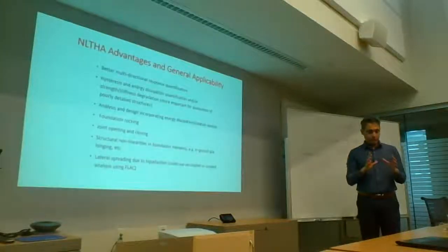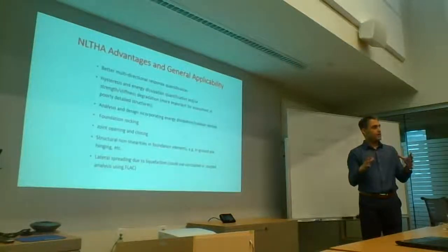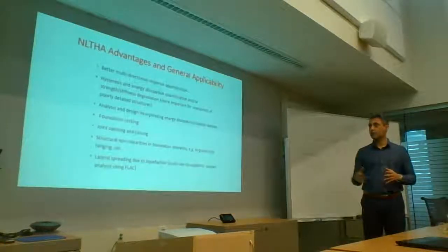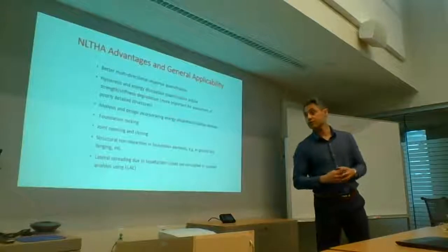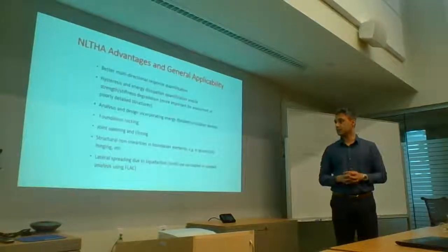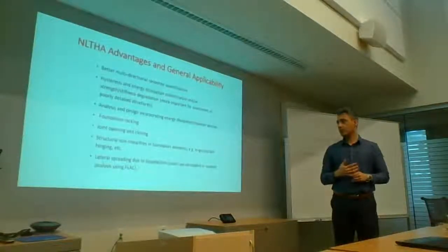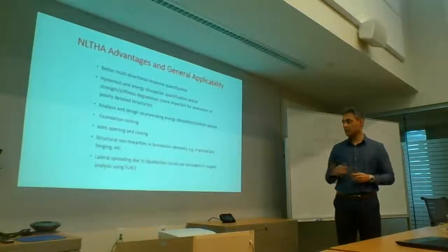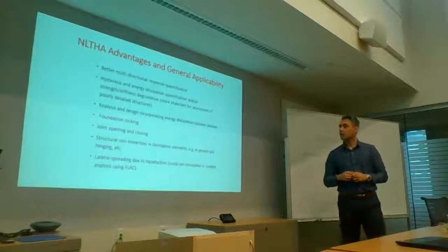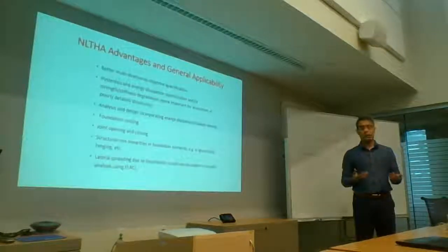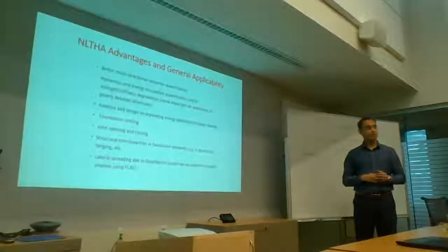But outside of those very narrow bounds, the code forces you to run a nonlinear time history analysis and not just do this based on pushovers and modal analysis. You're looking at foundation rocking or joint opening and closing, soil nonlinearities, lateral spreading due to liquefaction. A lot of that can be captured a lot better with nonlinear time history analysis.